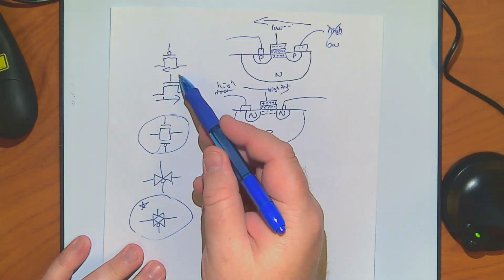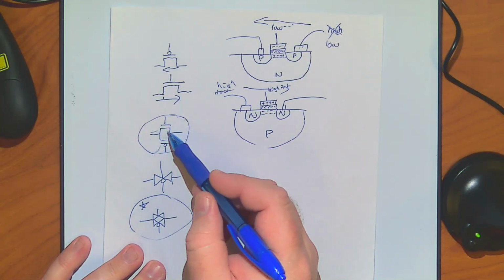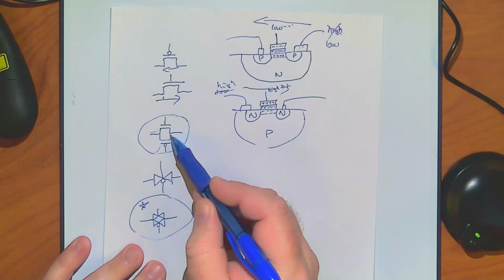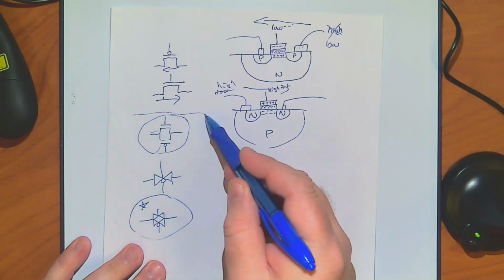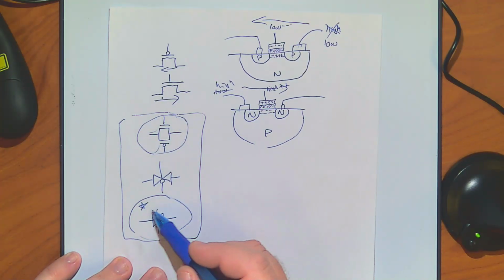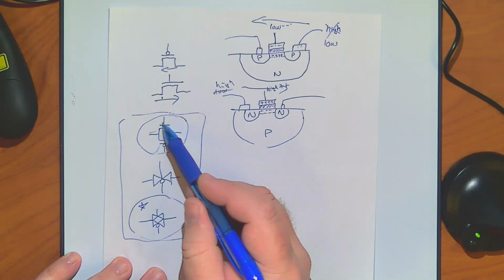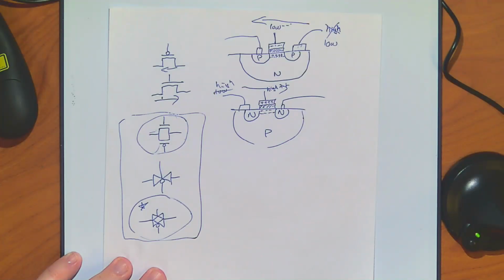And this is just the two ones flipped around and pushed together. So you can think of this as a wire, and you can see one FET, and you can see the other FET, and then the wire coming out. So these are the symbols we'll use to draw them. This is guaranteed for analog or pretty much anywhere for true bidirectional. This one is often in logic, and this one's a special variant. Does it make sense symbolically what it is and how it works?